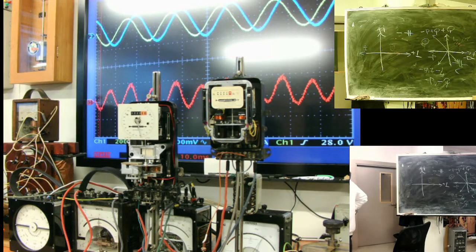Lagging. Yes. 90-degree angle, power factor 0. 0 active power, and you see the reactive power meter. Now it's reactive. It's running. If you consume much, you will pay approximately 1/10 of the tariff. You're now taking reactive power from the network. Yes. Opposite.